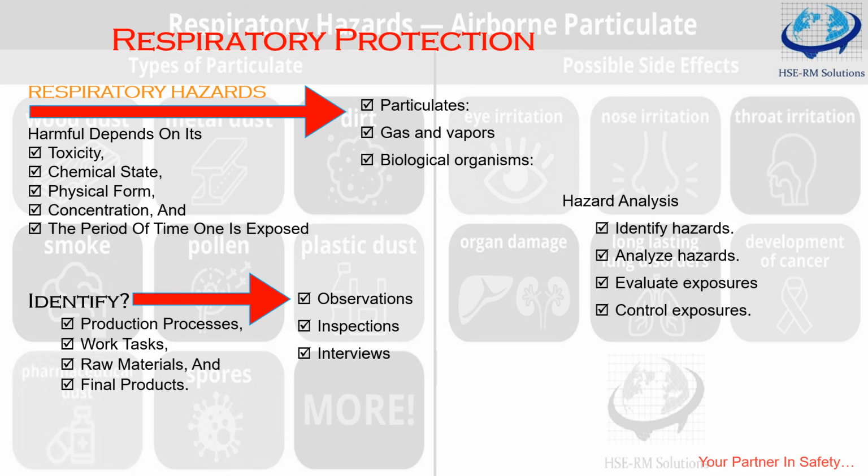Okay, say this is not possible. So the next strategy is engineering control. If you cannot eliminate or replace the respiratory hazard, use engineering controls to lower exposure to safe levels. Such controls physically change the working environment so the air is safe to breathe.